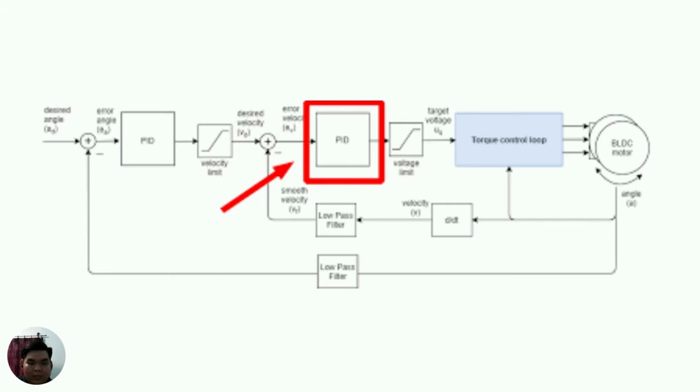Okay, in this picture you can see the closed loop system being controlled and tuned using the Ziegler-Nichols rule. It's a heuristic PID controller tuning rule that attempts to produce good values for the three PID gain parameters Kp, Ti, and Td.